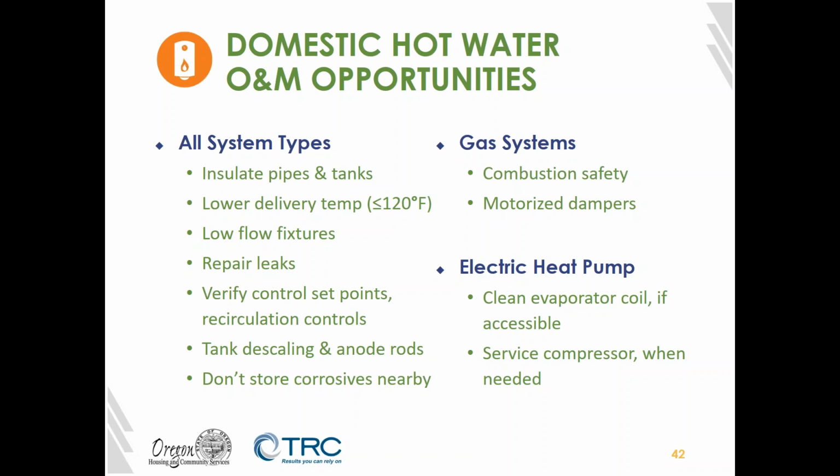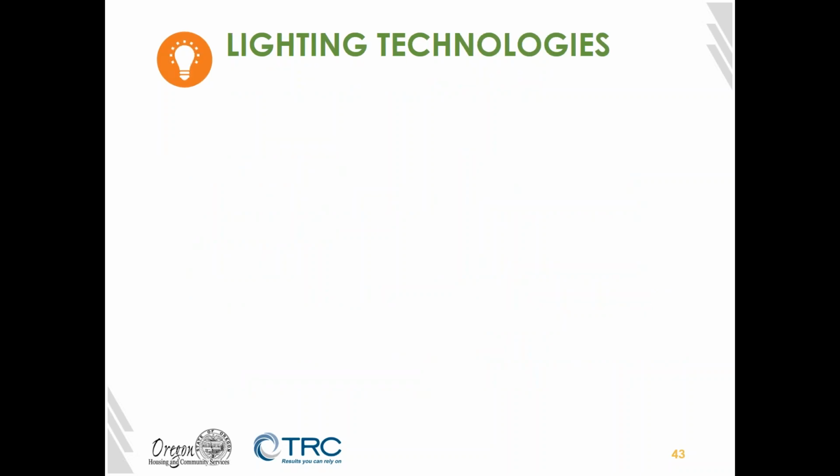Also, don't store corrosives near your water heaters or near your tanks, because they can release fumes that can degrade equipment. For gas-based systems, you want to do those combustion safety tests and also make sure that any motorized dampers are working. If you have electric heat pump water heating systems, you'll need to clean the evaporator coil just like you would for an air conditioner if it's accessible, and then occasionally you'll need to service the compressor as needed.